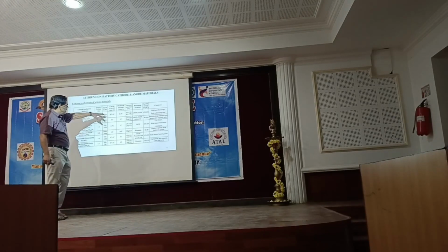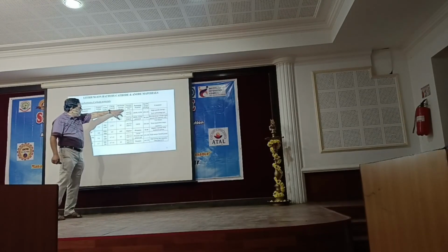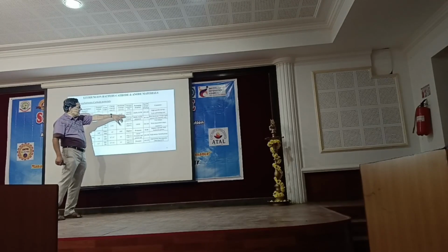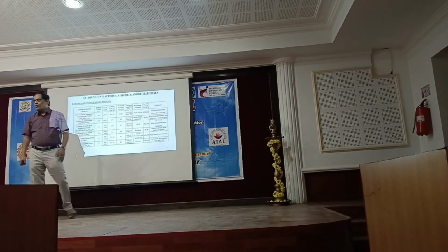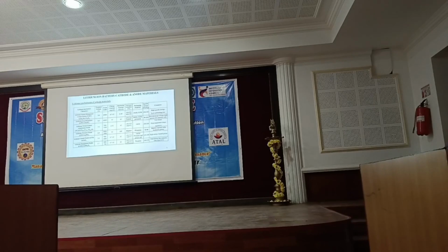Again looking at all the features: cycle life, at what rate it can be charged and discharged, what the temperature could be, what typical thermal dynamics can occur. We will never allow the battery to go to 210. Up to 210 your NMC can sustain, but with proper sensing of the battery pack through BMS, we never allow the battery to go to very high temperature. Above all, we have taken care of a proper cooling solution. Right now we use air-based cooling, active cooling and passive cooling. Now people are moving towards immersion cooling.